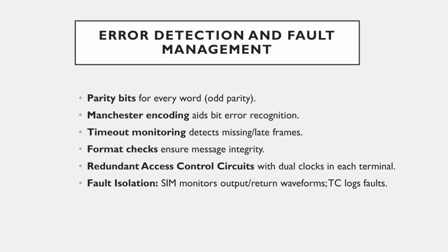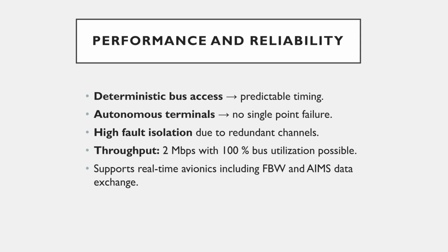The Boeing 777 uses 11 ARINC-629 buses, 3 flight control buses, 4 system buses for hydraulics, avionics, and propulsion, and 4 AIMS inter-cabinet buses. The AIMS computers also act as gateways and centralized maintenance processors. Couplers and bus assemblies are mounted on protected panels along the aircraft fuselage. This arrangement allows easier maintenance and reduces wiring complexity while improving system reliability.